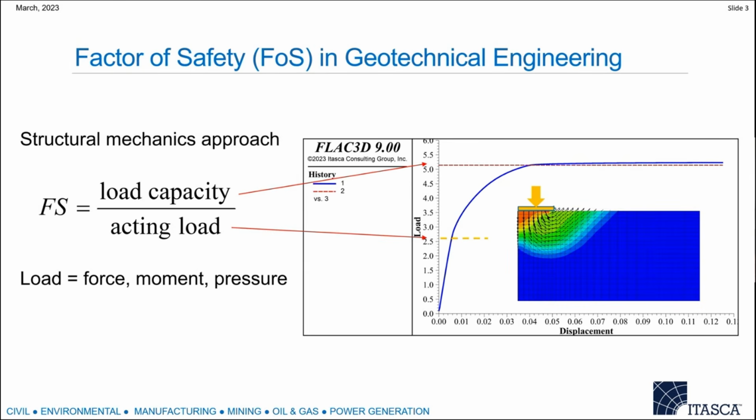Okay, first, factor of safety in geotechnical engineering. In these slides, we can see the classical Prandtl solution. This is actually a shallow foundation capacity calculation. So using FLAC3D, we can simulate the load versus the displacement, which is actually the settlement of the foundation.